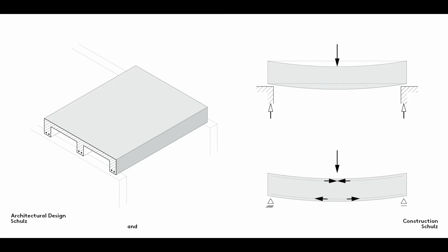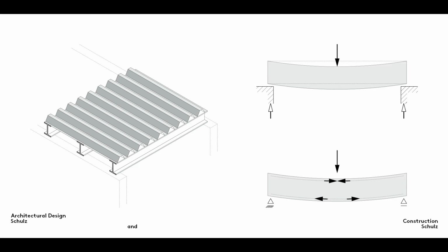Now let us take a look at the materials used. As for a solid reinforced concrete slab, here too reinforcing steel absorbs the tension forces that occur at the bottom of the members of a non-cantilevered slab. These members are known as beams or T-beams and the resulting floor as beam-type or T-beam floor. Their small construction depth is due to the fact that the pressure zones of both beams and slab lie in the same place. The construction is no deeper than the beams it contains. Because the reinforcing steel in the beams and slabs runs in 2 directions, the slab benefits from the multiple span effect.